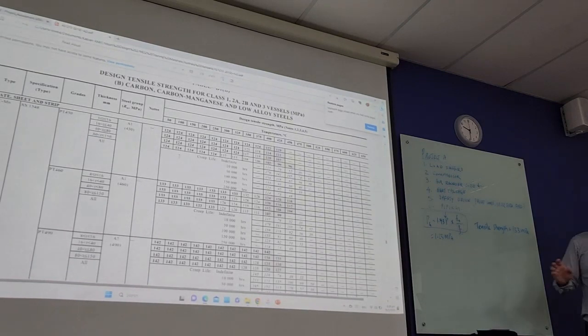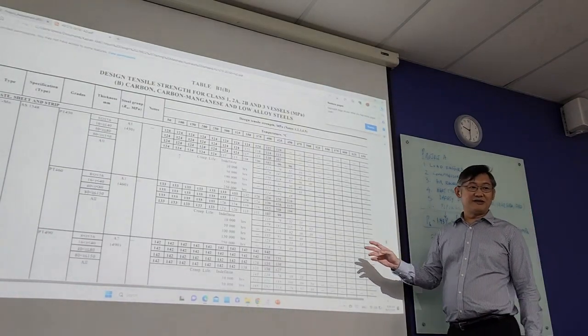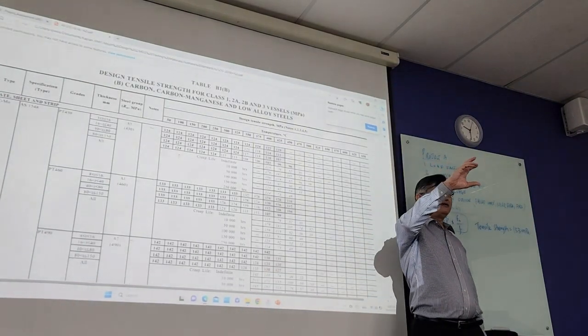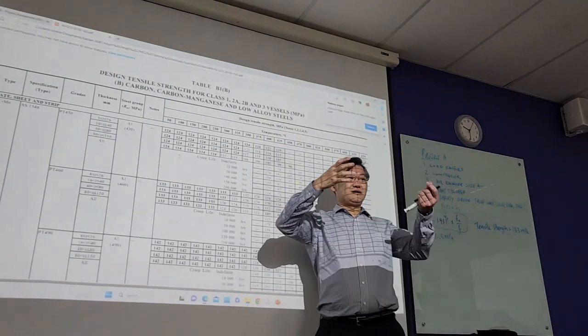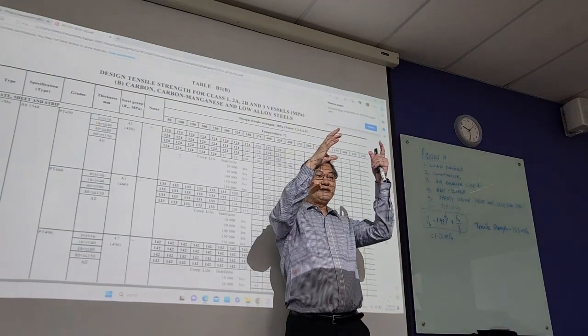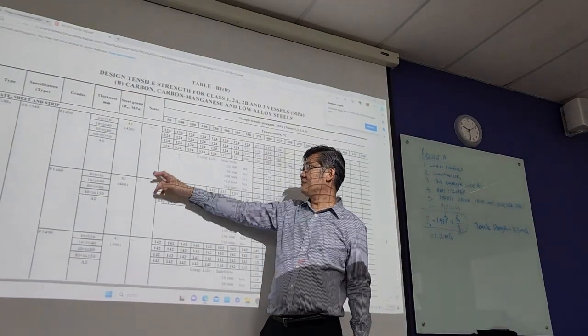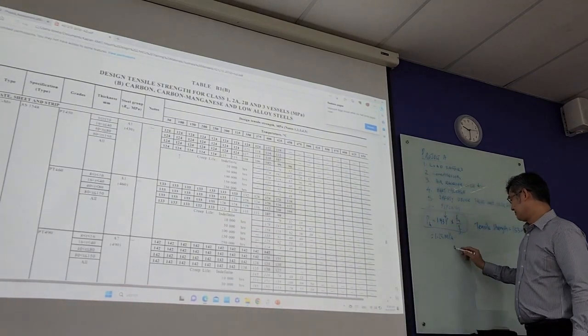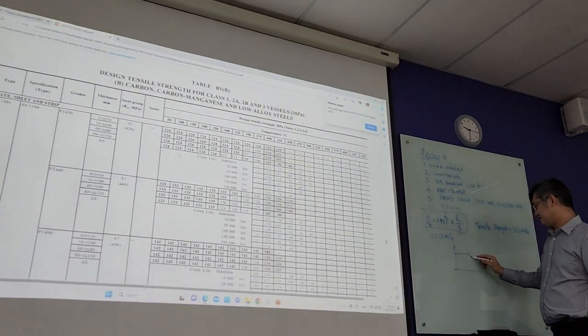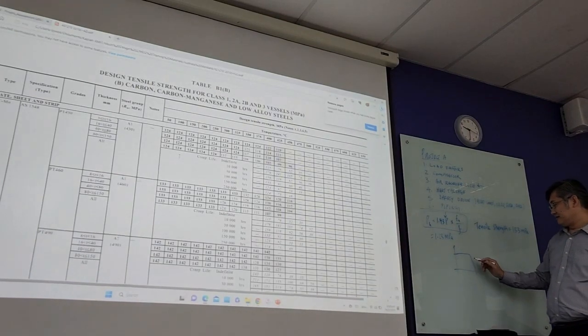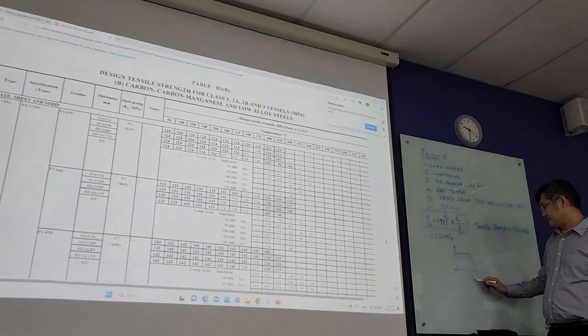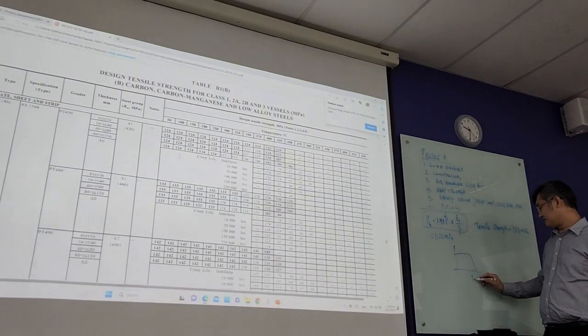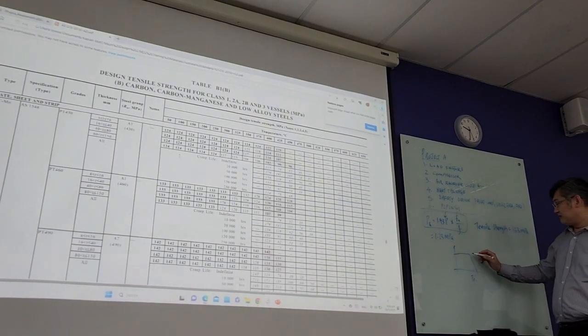And also for those who are doing project A, under fire condition, because when our receiver is subject to fire, it deteriorates. So you have to come here. You remember you have to plot the chart. This is the chart I show you. Then the TR value, the relieving temperature, on fire, you have to find out from this.